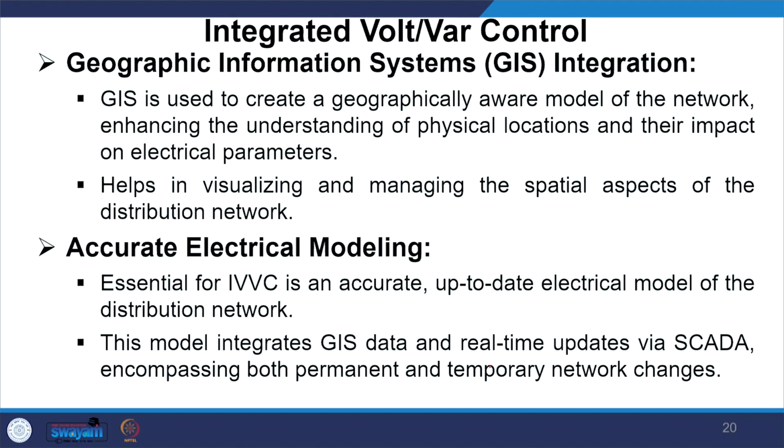Accurate electrical modeling is essential for IVVC. An up-to-date electrical model of the distribution network can be maintained through this process. This model integrates GIS data and real-time updates via SCADA, encompassing both permanent and temporary network changes.